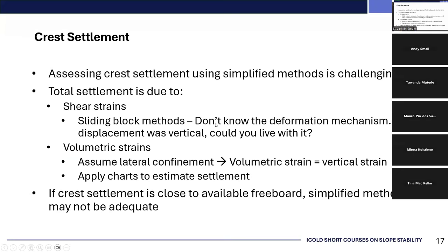that all works. So as a screening exercise, we often will say that the deformations that were obtained from these analyses are providing vertical deformations. Really, they're providing a non-vertical deformation, but you would have to resolve it to get the vertical deformation. But if you assume those deformations are vertical and you can live with them, then you're done. But if you need to go beyond that, there's ways to do it.